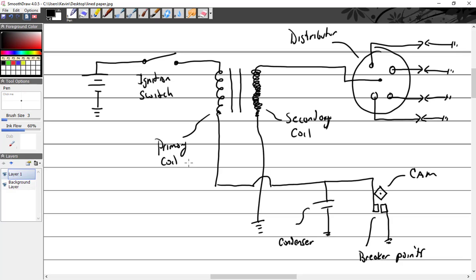All right, let's take a look at what happens. Now, this is a very important thing to remember. Is this currently on or off? It is currently off because the switch is open. Magnetos are the opposite. You will kill somebody if you don't get this correct. When a magneto is open, a magneto is on. So in this state, as I'm holding it right here, it is completely and totally on. Do you see a switch anywhere? No, there is no switch. So that means if I turn it, I will shock somebody.